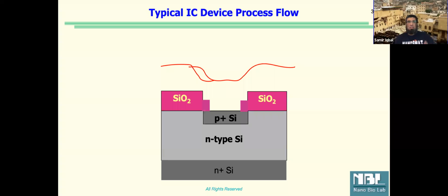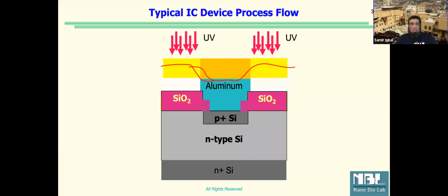Depth of focus tells us that on the surface of a chip, a microchip, there will always be different levels of heights. So when we want to project a design, we want the light to be in focus, or reasonably in focus, at all those levels. Hence depth of focus comes into play.